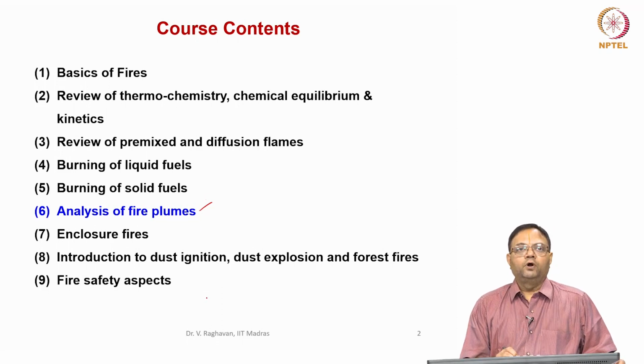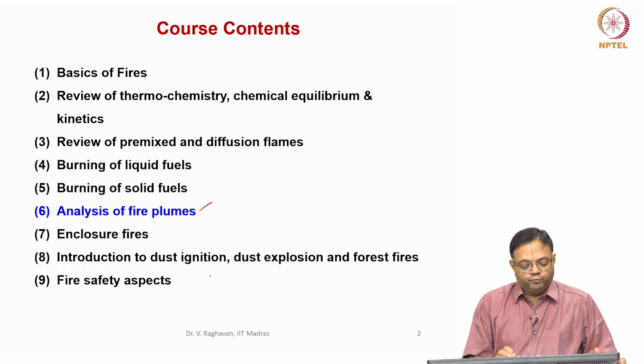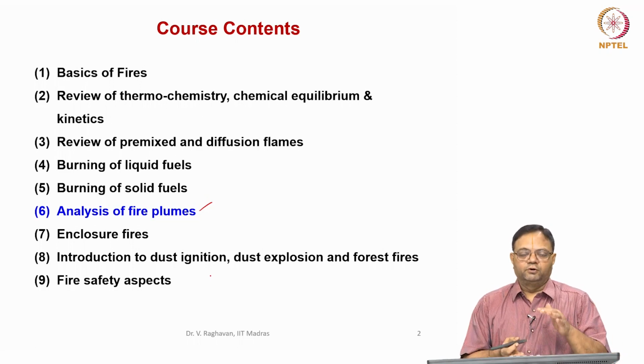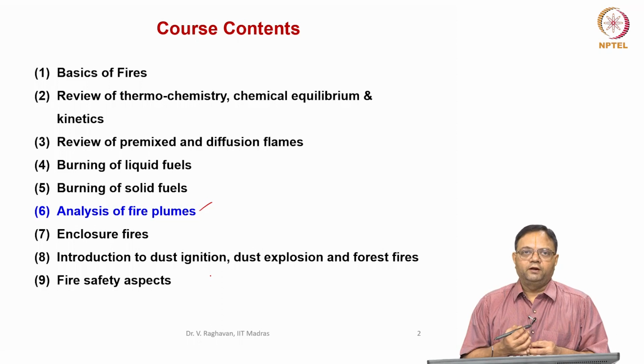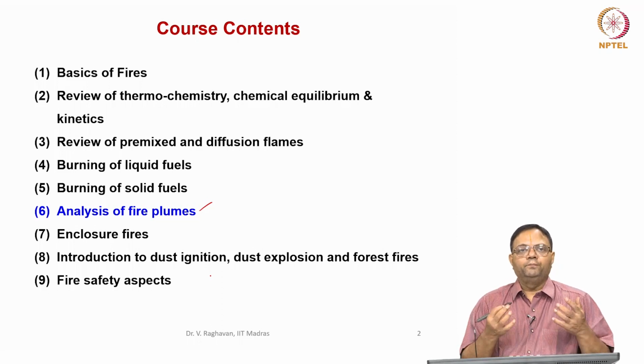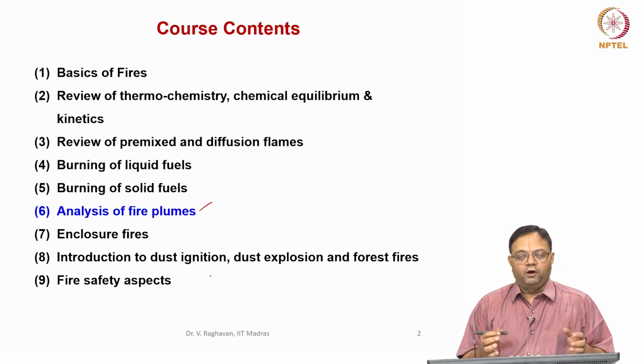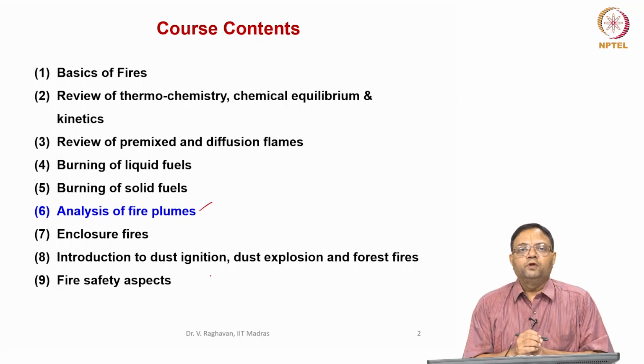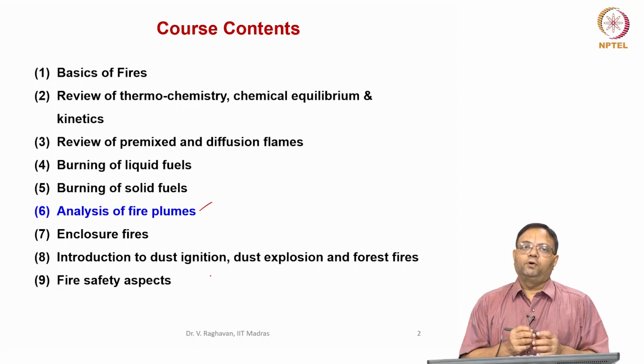How the fire plume is formed first. Okay, there is a combustion zone and there will be some oscillatory zone. Then the hot gases without much reactions will propagate, and due to buoyancy, you will see that these hot gases rise up, and this analysis becomes very important when you have a fire within a compartment.